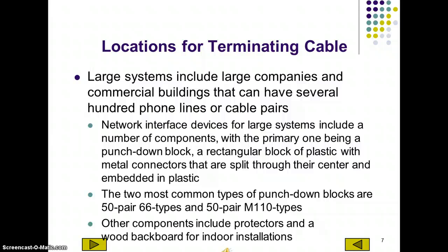We're using IDC style connections. Hopefully you know what that is. If not, it's insulation displacement connectors, and that's a common theme throughout the telecom industry. So we'll see different styles, but essentially very, very similar methodologies used in terminating cables around our facilities. Also, I've talked about the backboards. Hopefully you remember the specifications on those. 3/4 inch plywood, sanded one side, painted with fire retardant gray paint, and mounted very, very securely against the wall. With that, please read through the bullet points and move to the next slide.